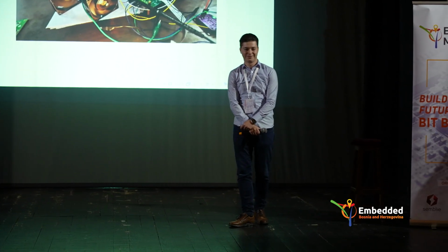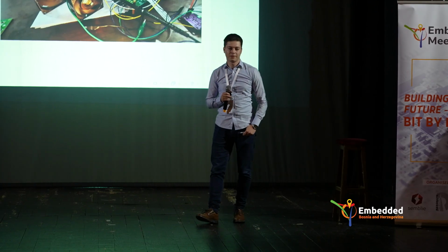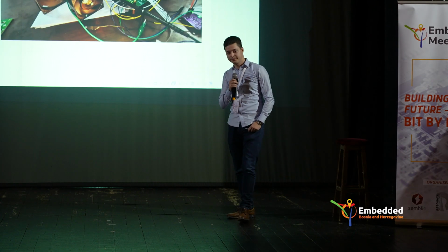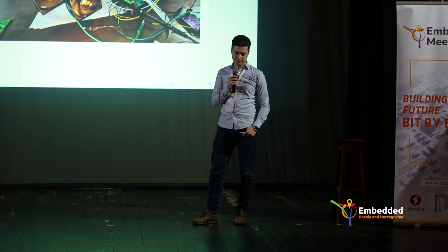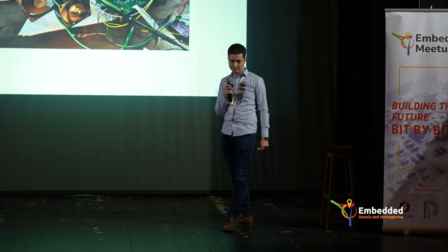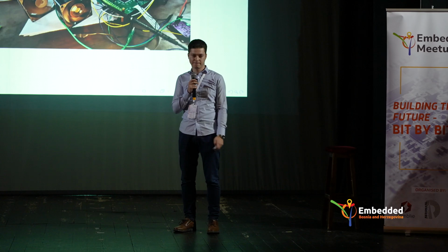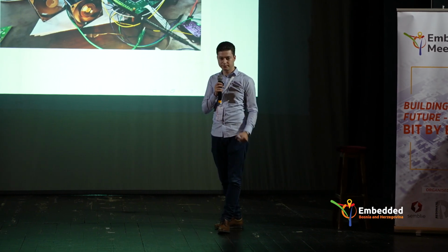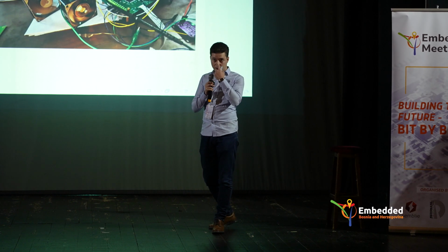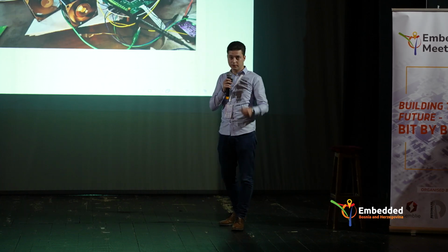Hi, great presentation, thank you. One question regarding the ping pong buffers that you mentioned. It's a great thing, but everything afterwards needs to be really time deterministic. Everything needs to fit in the time for the ping buffer to fill in again. So how did you measure that? Or the other choice would be a FIFO buffer. So how do you know that you don't need a FIFO?